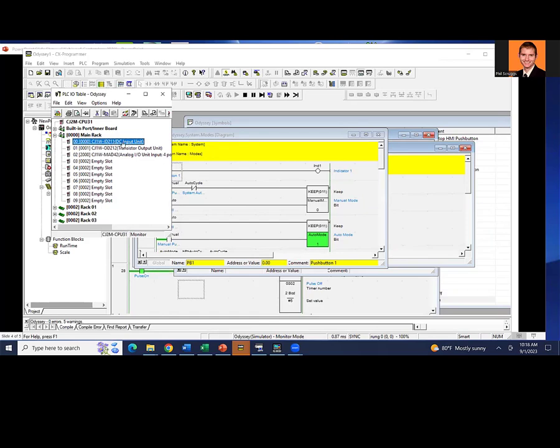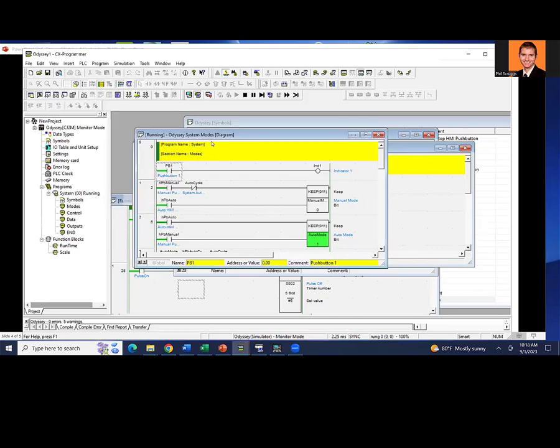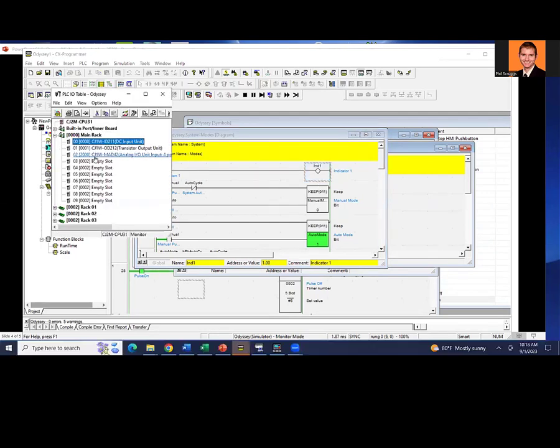So if I want to test the real push button, I go here and I type 0.00, and this is showing you that down here. That's the address. The name of it is PB1. That is a symbol. And then here's the output. And the output is at 1.0. And so again, when I go to my IO table here, you can see that the output was set to 1. And so these numbers here, 0000, that is the CIO, just register-based address of the IO. That's pretty unusual.